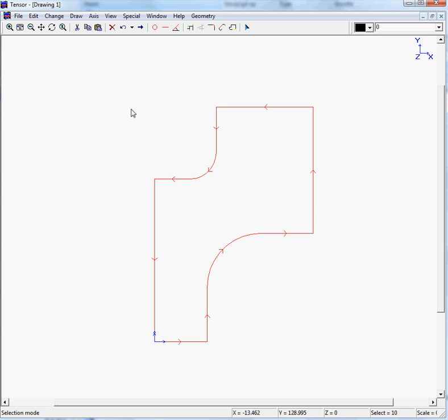So remember, from this exercise you can use the line sketch function to sketch your horizontal and vertical lines. Use the fillet function to define a rounding between two elements, and remember the close chain button, which will take care that when you trim, you will not only trim the elements in order, but also the last element to the first element. Now move on to exercise 2.